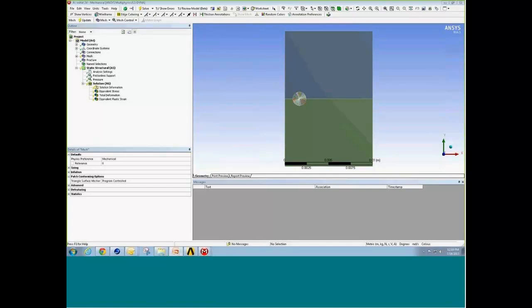The first one is going to be a pre-meshed crack. That means you've built your geometry such that the geometry contains a crack in it. And you can do this in 2D or 3D. So if you've already created geometry, or if you already have a mesh, you can bring it in through FE Modeler and then just identify where that crack is. And that's what I'm going to do. And just to make this fairly easy, I'm going to do a 2D model, just for time's sake.